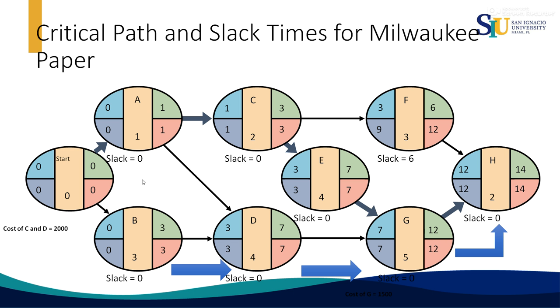Then when there are 2 critical paths, the method says for the critical activities, select the one with the least crash cost. In this first path, you can verify that it's activity C with 1,000, and in the second one it is activity D with 1,000 also. Then 1,000 plus 1,000 is going to be 2,000 because you have to add the two critical paths.